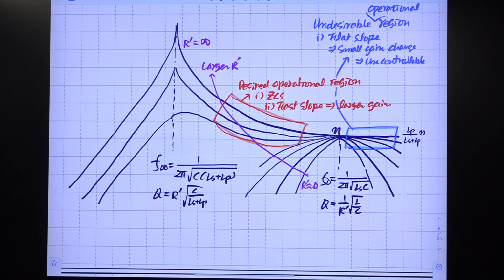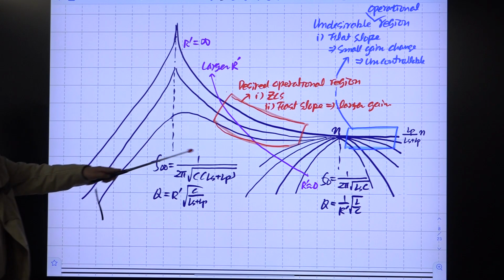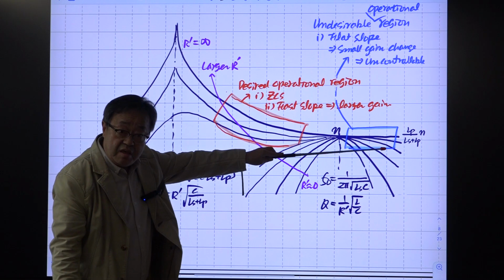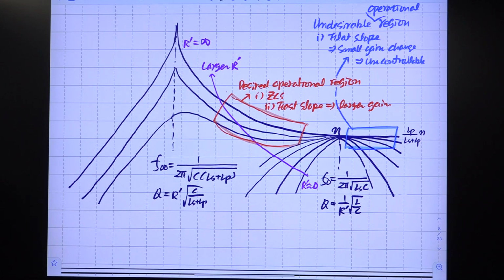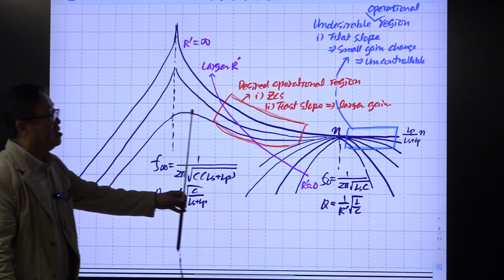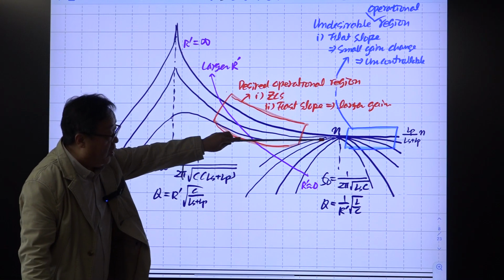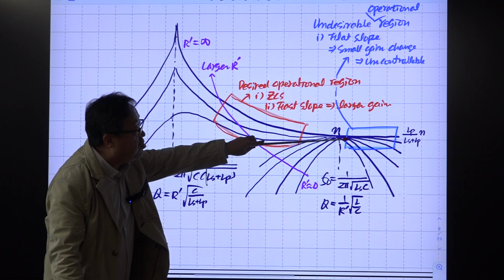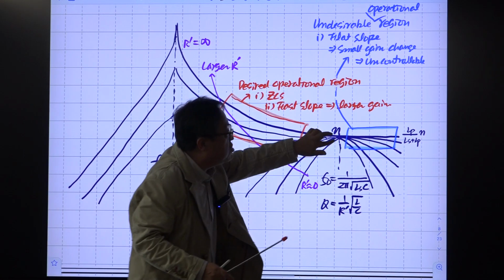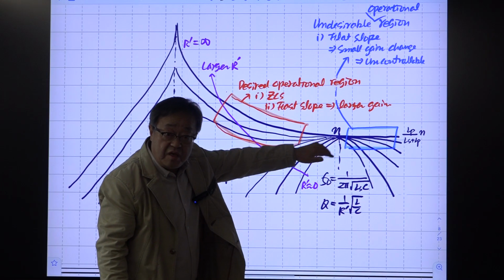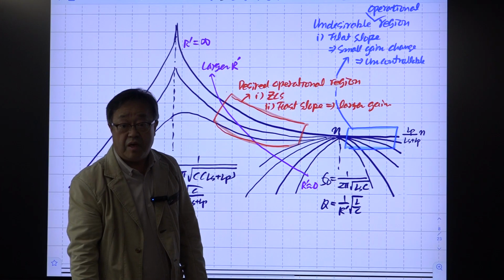That means the gain of the control to output transfer function becomes very small. If this is flat like this, we cannot control the output, right? To control the output, if you change the operational frequency, this gain should change. But in this frequency range, if you change frequency this much, the gain is changing only this much. That means you are losing control, okay?